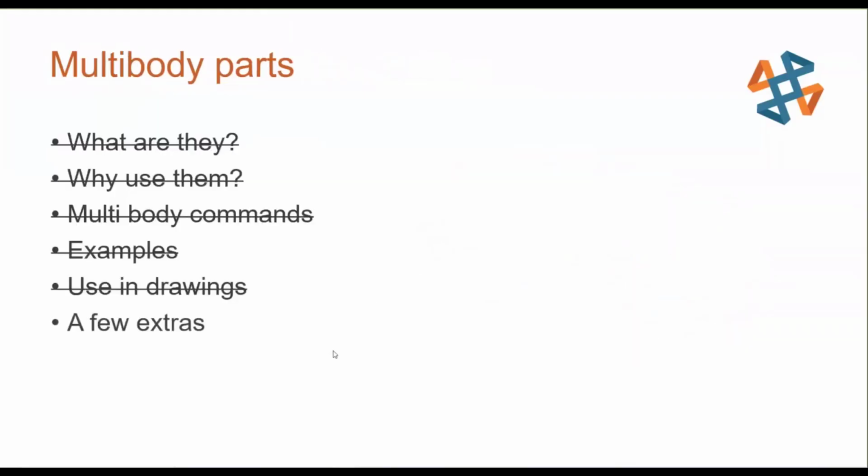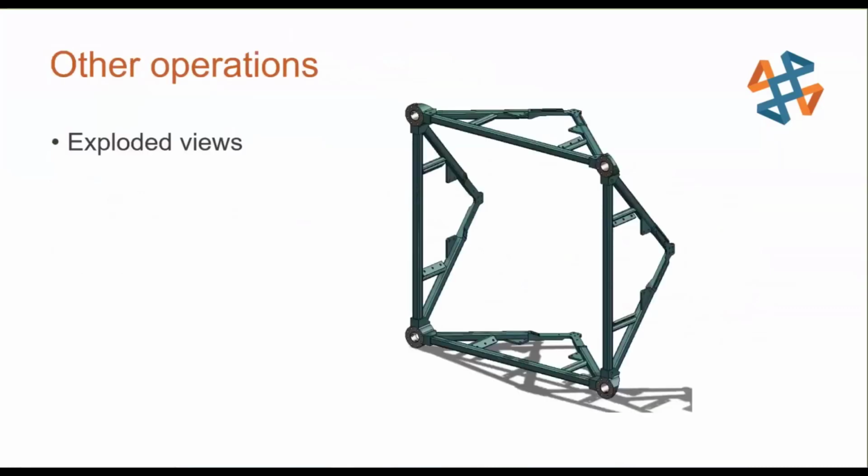All right, last but not least, a couple of extras. So exploded views. Yes, you can create an exploded view in a multi-bodied part the exact same way that you can in an assembly. You cannot animate an exploded view, though, nor can you create a video of that animation of an exploded view for a multi-bodied part like you can for an assembly. But you can do it.